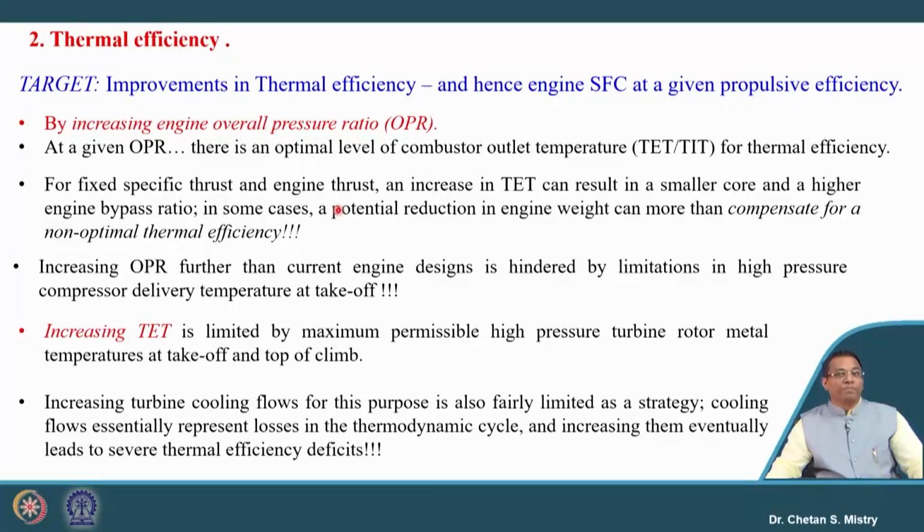Suppose we are looking for a fixed specific thrust, and if we increase the turbine entry temperature, that will result in a smaller core and a higher bypass ratio engine, and that will help us in achieving the thermal efficiency. What we are discussing at this moment is what has been implemented. So, in all these 5 lectures we will be targeting all these aspects. We are making the background first, and then we will discuss how engine manufacturing, engine design and engine research companies are working on this.